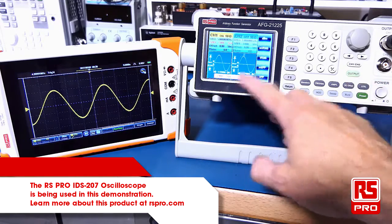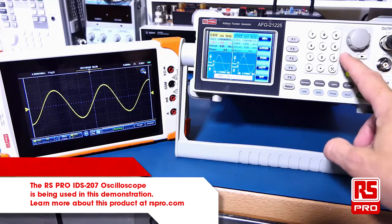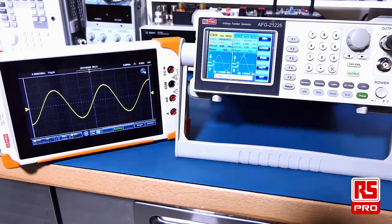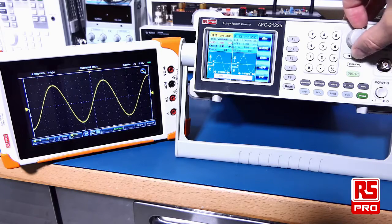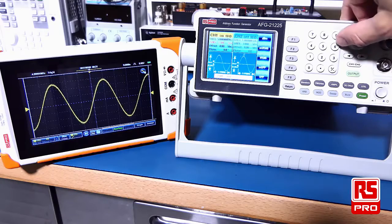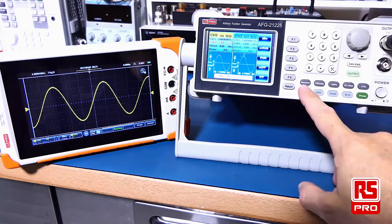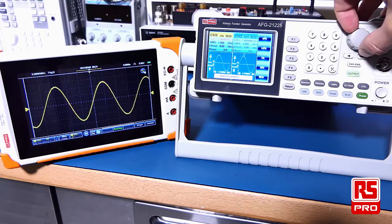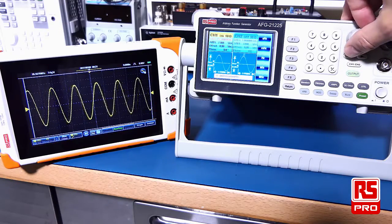Slight modifications to your parameters can easily be done with the rotary encoder. Simply use the navigation keys to select the digit you want to work with and rotate the rotary encoder to make those changes. In this case, the amplitude of the signal is being altered. We could go back to frequency and again using the rotary encoder, make changes to that.